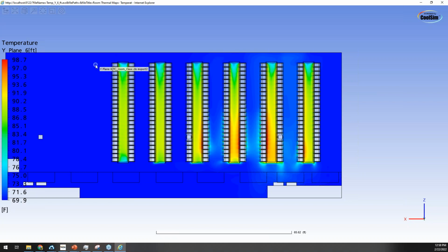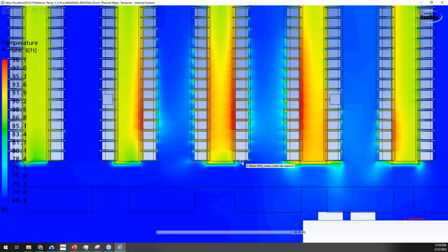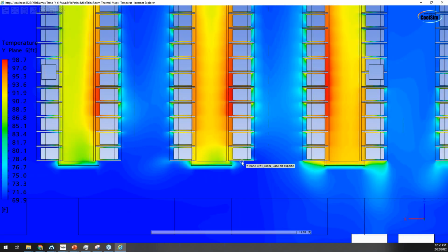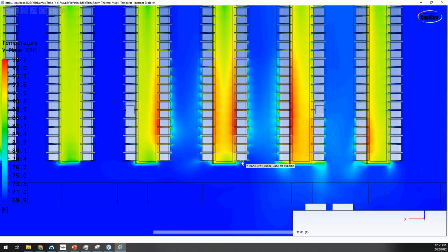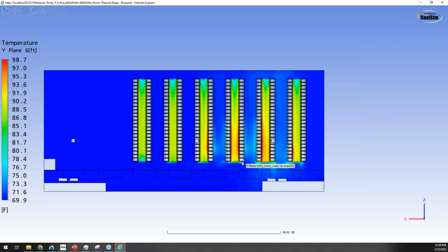They'll often encourage you to not add any leakage or reduce leakage. There'll be no leakage. And it is our job, I think, to remind them with images like this that there will be leakage, and leakage will cause the performance of the data center to degrade. You'll end up with hotspots, particularly in N+1 cases where you've got one of the air handlers off. And it's important to model so that you can show them.